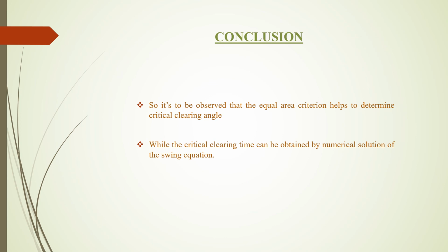So now we can conclude that it is to be observed that the equal area criterion helps to determine the critical clearing angle, while the critical clearing time can be obtained by numerical solution of the swing equation.